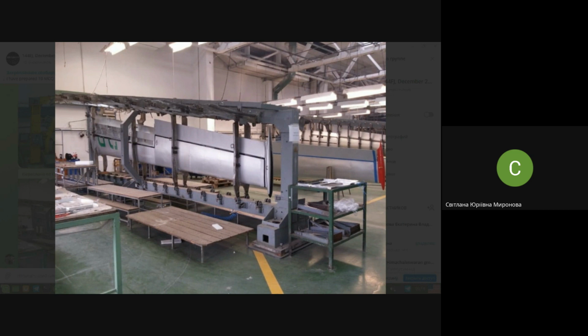Jigs are responsible for producing separate pieces of airplane aggregates that in final assembly meet and join by places of junctions, whether it's flange junction or fork junction or telescopic or whatsoever kind of junction. We need to just attach two pieces and they coincide, mating, matching, automatically. At sizes, they are identical.